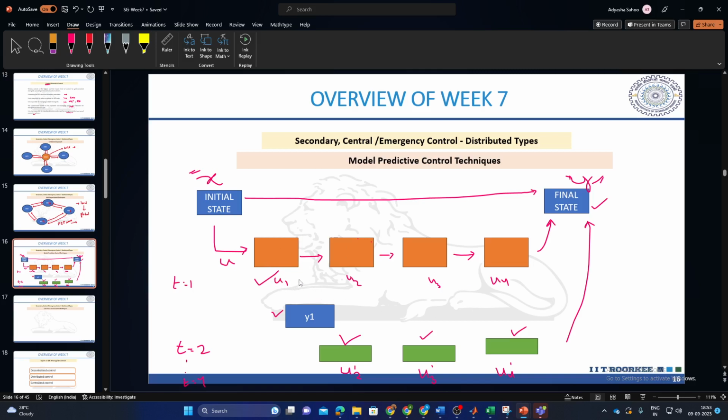So again, the model predictive controller will take into account the new initial state where one generator is now out. So considering that generator outage, and again my final state as where the lines are not congested, it will give me a new set of control actions. And by this, in steps, we will reach our final goal, that is when there is no congestion.